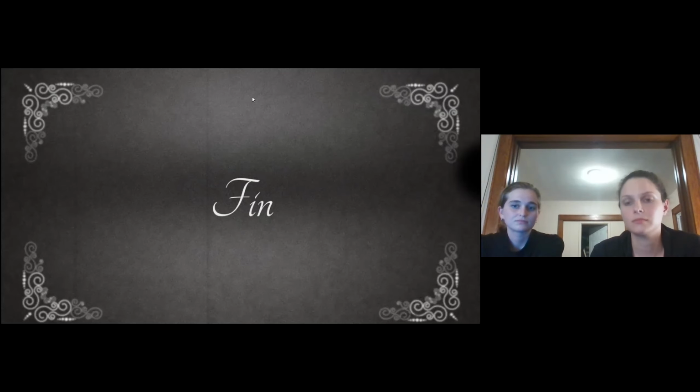There's a lot of small details and flexibility in how to apply fixtures that reflect your real-life situation. So understanding which fits best, and when to choose, is this a bound contact? Is this no penetration? A lot of small details add up to make your total model good or not.